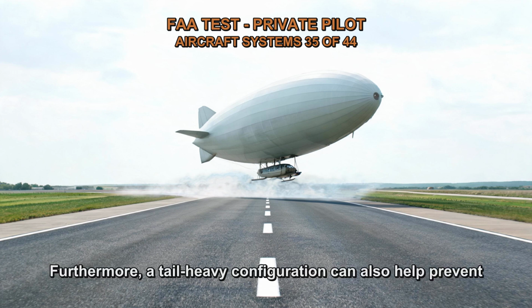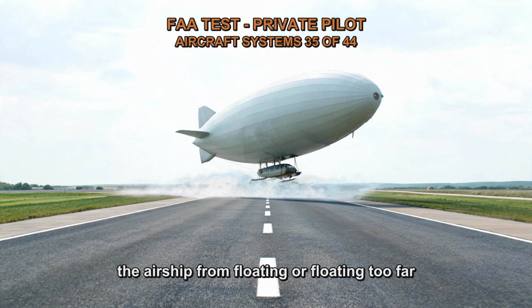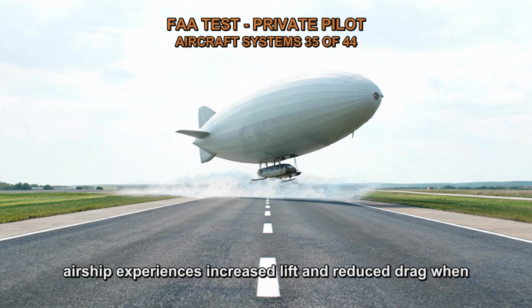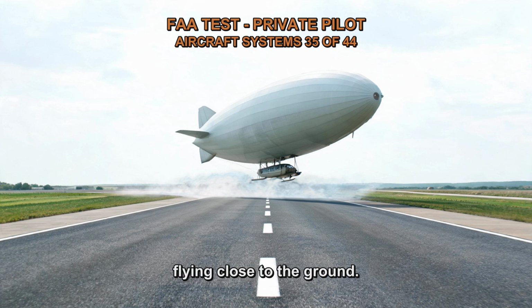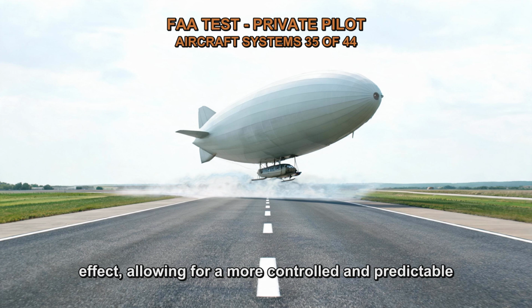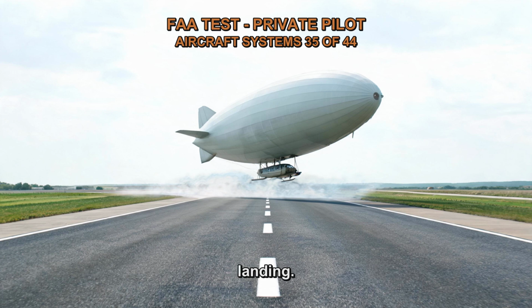Furthermore, a tail-heavy configuration can also help prevent the airship from floating too far during landing, as it aids in reducing the ground effect. The ground effect is the phenomenon where the airship experiences increased lift and reduced drag when flying close to the ground. By being slightly tail-heavy, the airship is less likely to be affected by the ground effect, allowing for a more controlled and predictable landing.